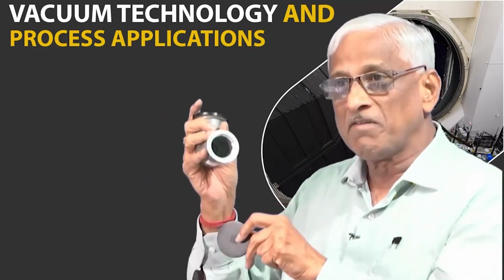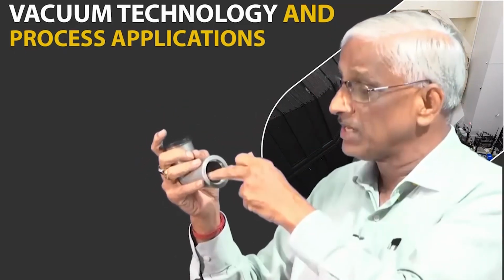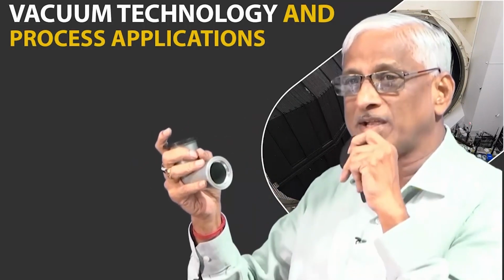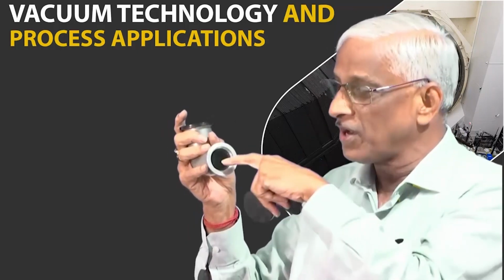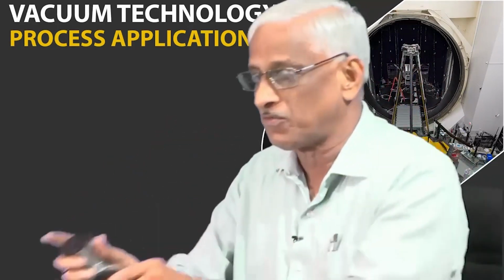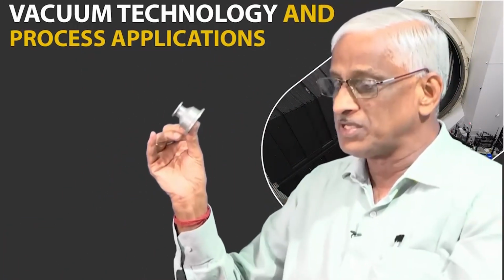So, you must be very careful, and you should not sweat, because if you touch it with sweat, it will form a monolayer; at 10 power minus 9 torr, it will take 10 days to get 10 power minus 10 torr, and if you do it with gloves, it will come to 10 power minus 10 torr maybe in 1 day. So, you have to be very careful, and at times from a larger diameter to a smaller diameter, a reducer is required.